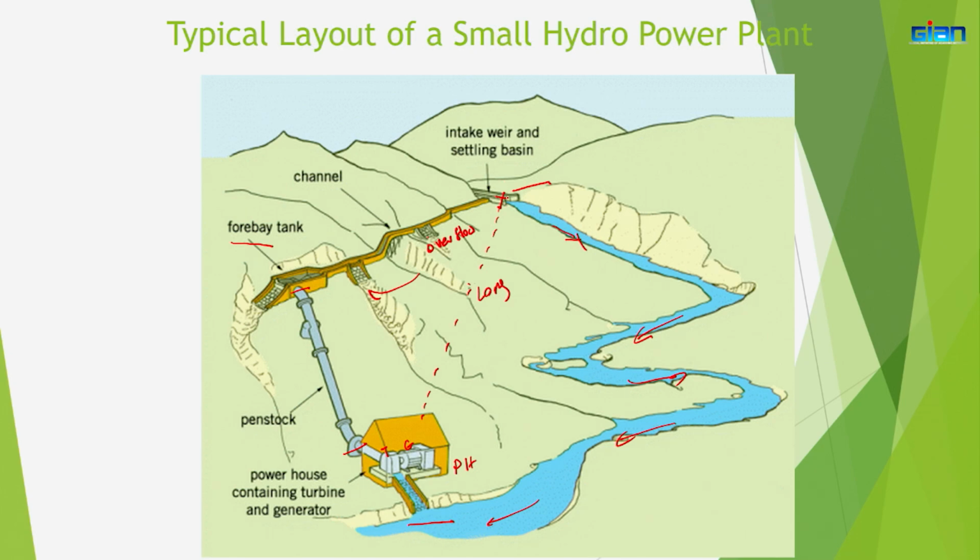So, when we divert water, we will provide the major water component to the canal, but we will release some water into the river as well, what we call the environmental flow, to keep this river section from A to B, again, we do not want it to be dead, right, without water.